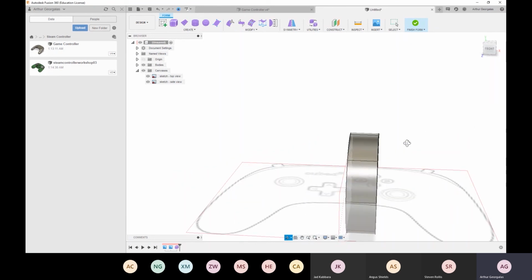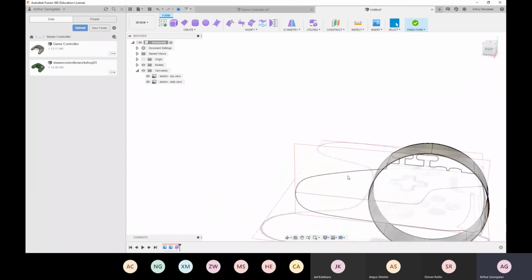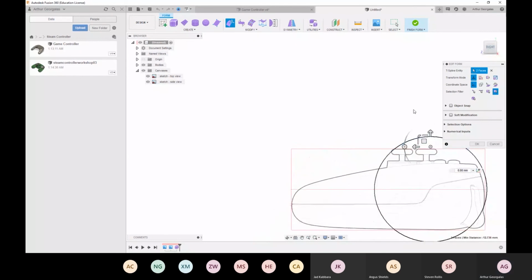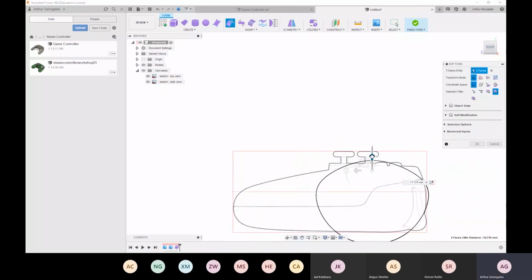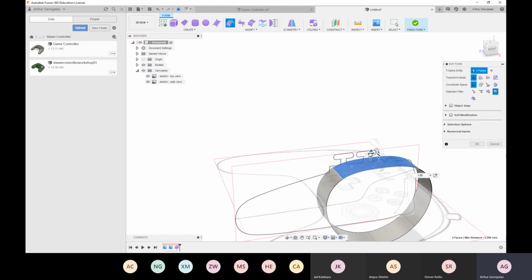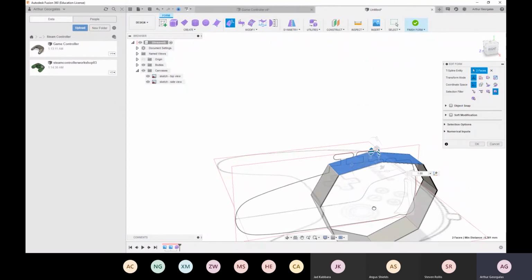And I'm going to model up 1/2 at a time because we're going to mirror it in a minute. What we want to do from there is modify it. So edit the form. We can grab the top, pull it down. We've got this thing here which flattens. So what that does is flattens or extends how these surfaces work. And if we look at them in the box mode, we can see it just drags that completely flat or stretches it out. So that can be really useful.